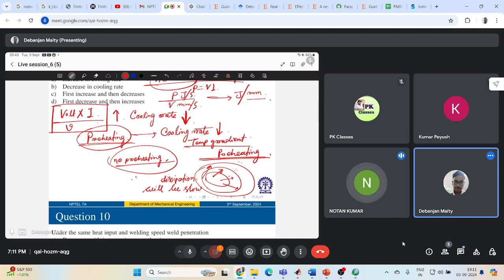How can we increase the hardness of these types of metal? Actually this question is a little out of scope, but fine. I will talk about precipitation hardening, and I'll also talk about work hardening, because of cold deformation. Now in steel, transformation hardening is a more general term used for something called martensitic hardening.